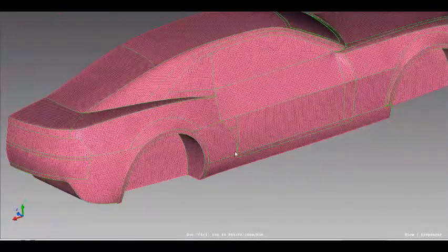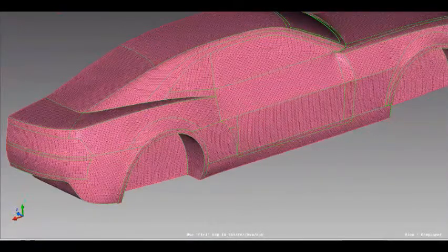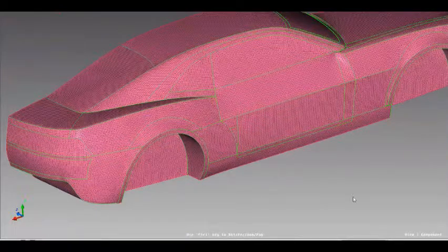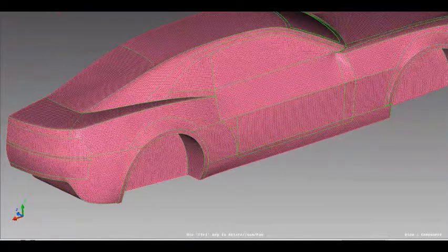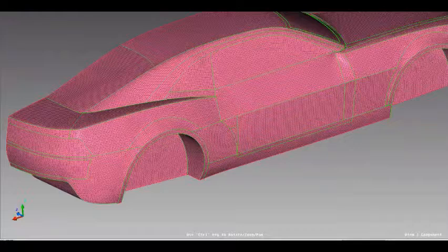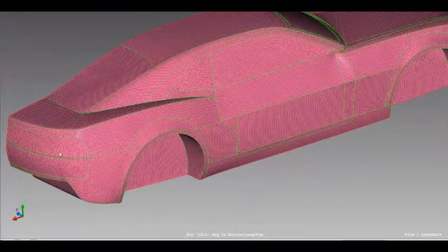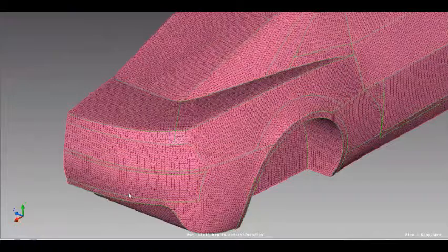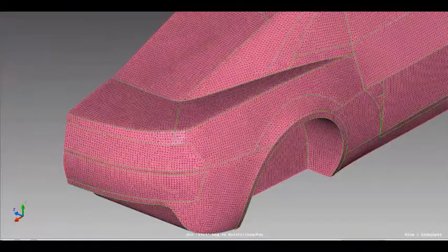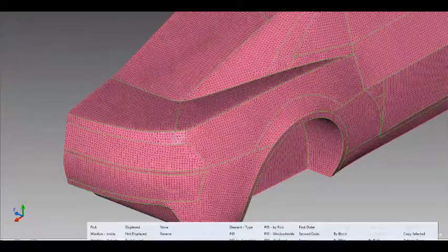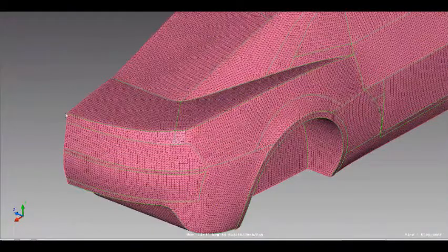Now I'm going to move on to the next demo, which is auto parameterization of the external surface. So for that I'm going to morphing, parameterization. So I'm going to set up the morph set here, and I'm going to use a field-based morphing. So the first step, I need to select the control nodes. So I'm going to select by nodes by path option here.